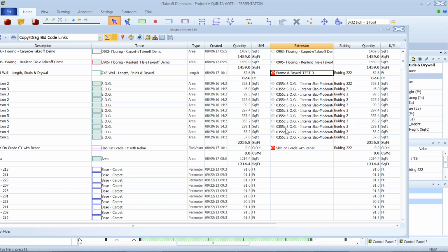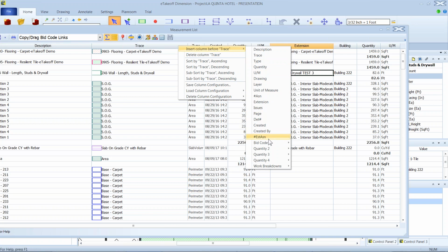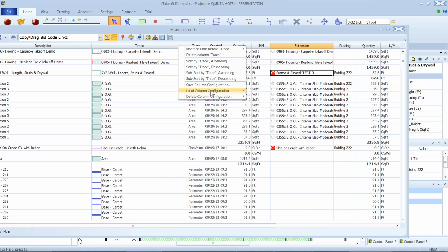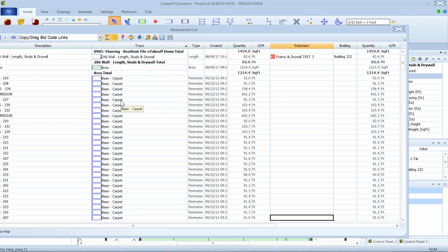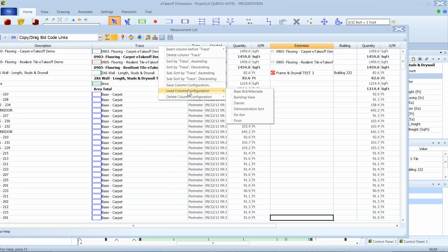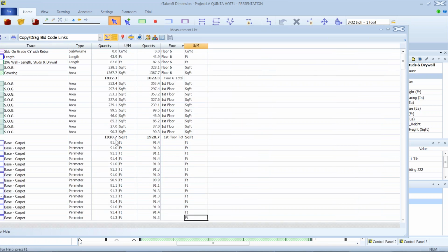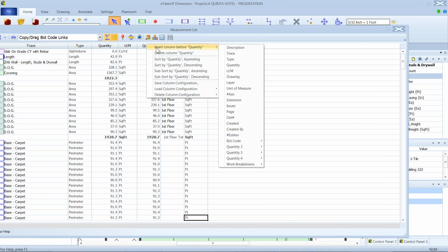Now, if you start to think about reporting over here, we can do so much within our estimating software, break it down by WBS codes, and so on and so forth. So I can massage the information the way that I want. This solution is going to give you the opportunity to track all of these particular columns, these particular fields right here, even work breakdown structures if you want to. It'll allow you to load up those specific ones you want to see over and over again. So in my demonstration, I'm going to sort it a different way. Or if I go into floor, I want to see it broken out by floor view. So I can see floor 6, and so on and so forth. This has the most robust reporting tool within any solution that I've ever seen as far as digital takeoff is concerned, and it's so easy to work with.